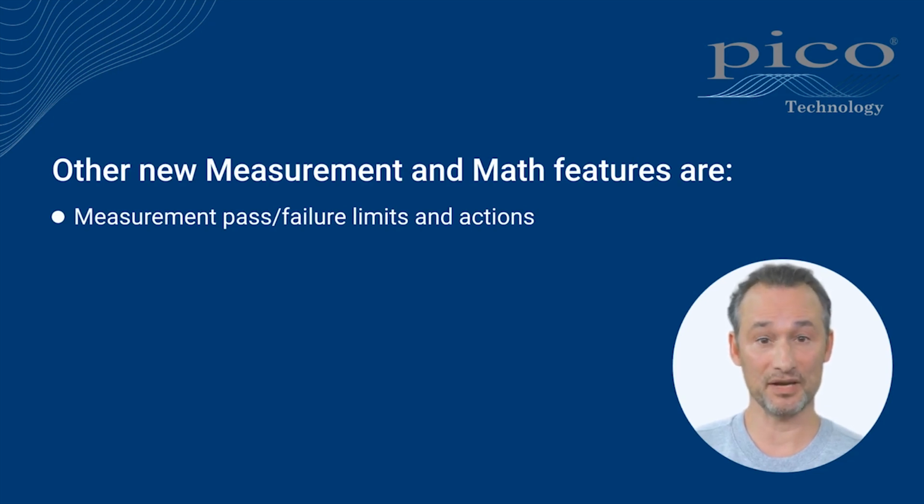Actions include stop the capture, save waveform to disk, play a sound, trigger the signal generator, run an external application or script. So, for example, the instant a measurement falls out of specification, measurement pass/fail limits utilize actions to save the waveform file and trigger a debugger so that circuit failures can be correlated with specific points of program activity. This automation can also be used to streamline production testing activities, saving valuable time.